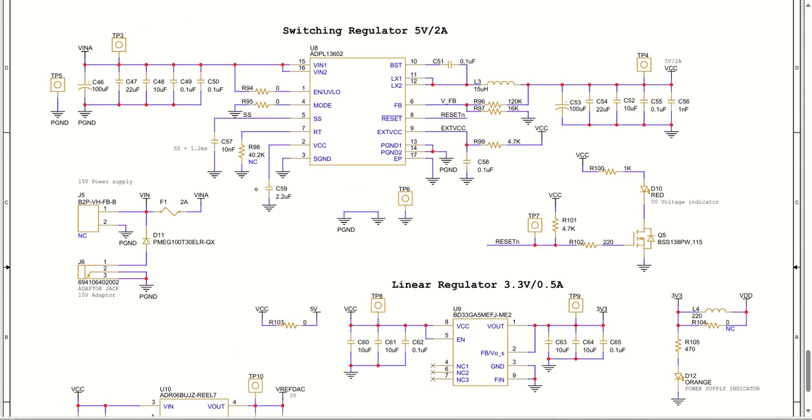So as you can see, this is the power supply connector. You can connect 15 volt directly here with a huge safety. It is going to VIN A here. Otherwise, if you have an adapter jack, you can connect a power adapter directly, and through this it will come to VIN A. So you connect a 15 volt power supply here, so that you directly get 15 volt.